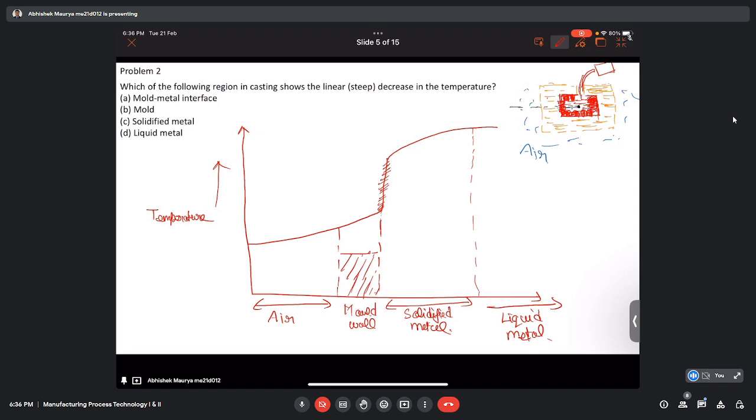So something like that. The dark red hashed region is the solidified metal, whereas the center there is the liquid metal. So the center there is liquid metal, that is this zone which I am showing, and the red hashed region which I am showing schematically is the solidified metal which sticks to the mold wall, that is this region.